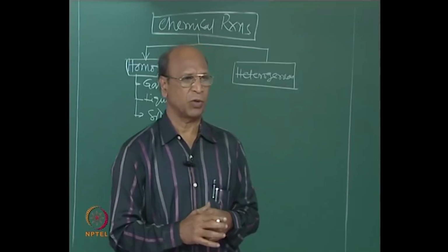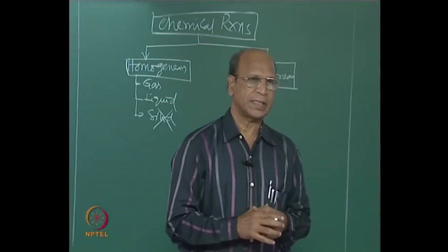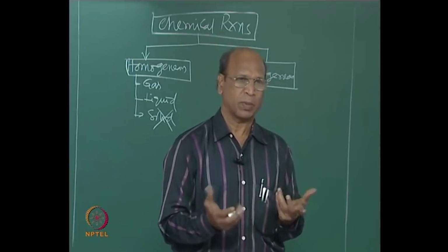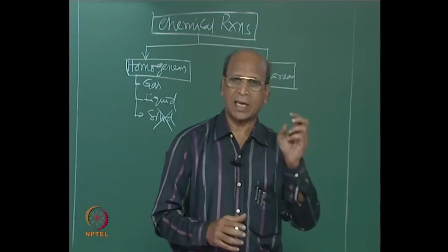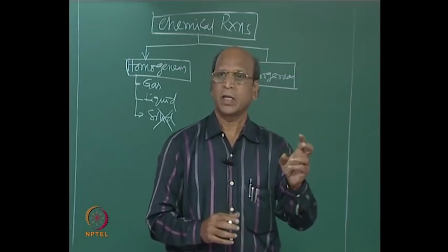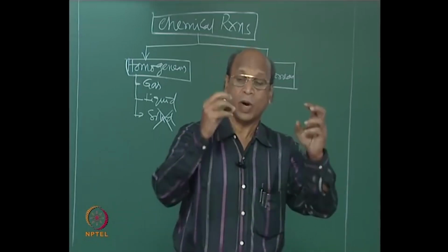Properties should remain the same, like concentration. Yeah, but still, what is the meaning? Okay, they are remaining the same. So what? So determining kinetics will be much easier. Why? Because properties remain the same. At one location it would be different, and at some other location it would be different. That comes as mixing. Properties the same means concentration the same throughout, but the basic requirement in a homogeneous phase is that the molecules should be readily available for reaction,